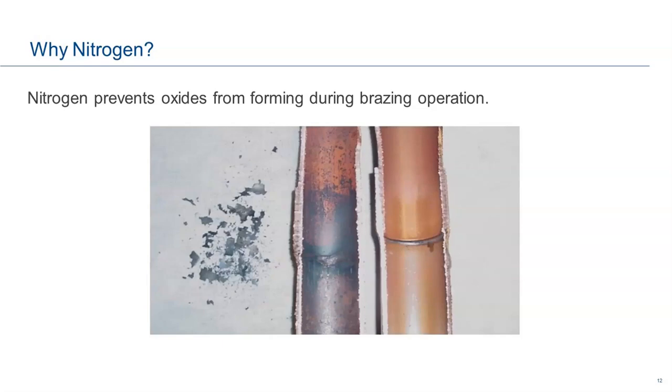POE oil, because of the way it's made, it is like a flush, if you will, okay? It will make something like this look like that, okay? When mineral oil's around, things would fall down and get into a corner to hide themselves, never be seen again. But with POE oil, it picks it up and moves it on down the line, okay? I always use a snow globe, which is one of the best analogies I have ever heard. You take a snow globe and you shake that snow globe, and those flakes are hitting the ground. When they hit the ground, that's mineral oil. But as the flakes come down, if it's POE oil, it picks those flakes up mid-air and takes them on down the road, okay?